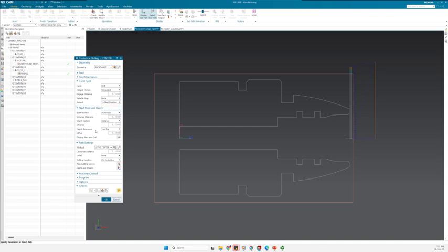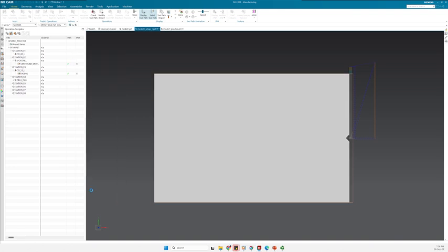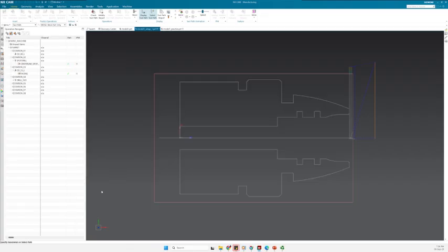From the starting point and depth, I can define it based on the tool tip or based on the tool shoulder. Of course, when we are defining by the tool tip, I need to calculate or also make sure that the part is completely penetrated, because there is a conic shape at the tip of the tool. So maybe it is easier to consider the shoulder for me. And I know that my whole total height of my part, or let's say my raw stock, was 155. So I would just put 155 and then check it out again and verify it.